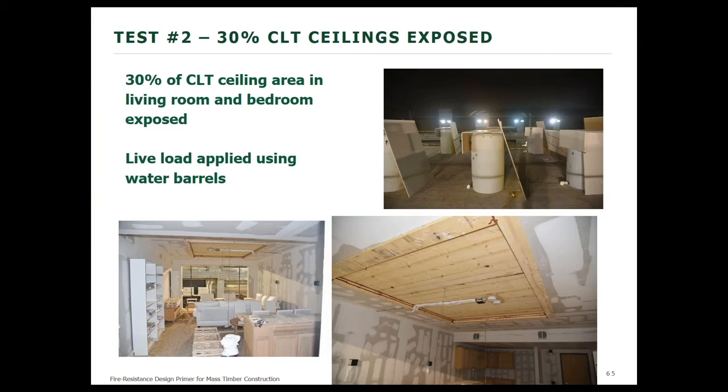Now on to test number 2. Again, to refresh, this is where we had 30% of the CLT ceilings exposed. The exposed areas were provided in both the living room area and the bedroom area. The live load, to identify that the load carrying capabilities were not affected, was applied using water barrels.